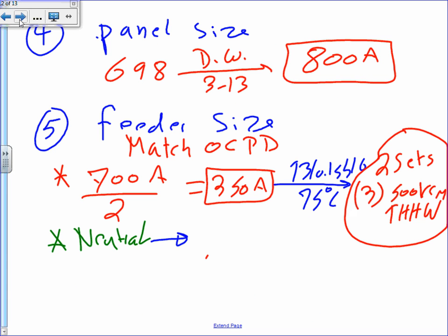So let's add them up. Help me here, guys. I'm going to put my neutral load. My neutral load was 219 plus 19 plus 1.5 plus, and I did not do this step, plus 50 plus 24. Am I right? The only thing we dropped is just the 265.8.